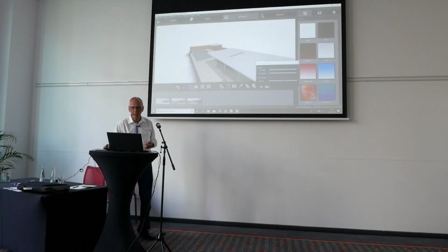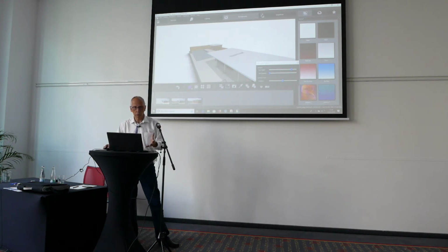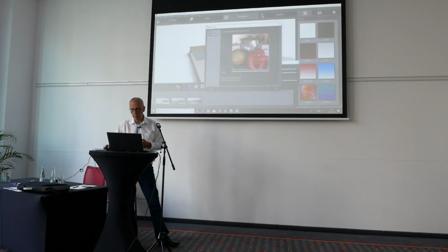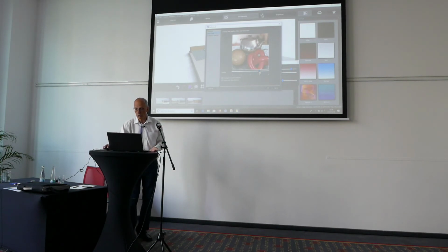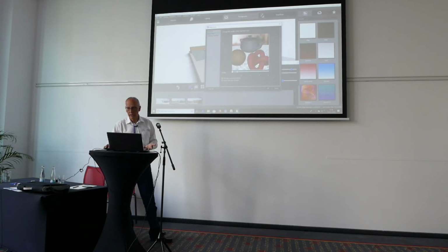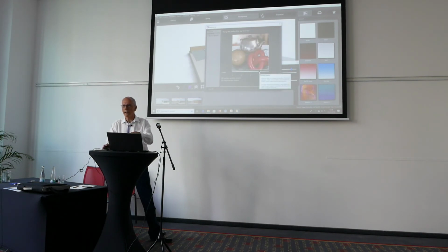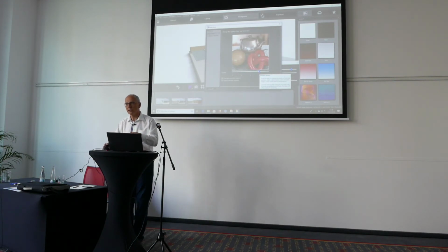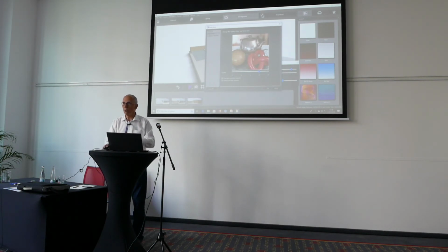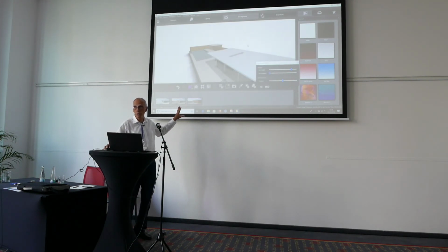And we do actually have an interface. I know some people sell a machine which may not be able to do all of this. I think in the edit preferences, we can say, okay, the real time, at the moment, oh, I've got it on 4, it's not even as good as it can be. So we can change the quality of the OpenGL rendering according to the card that's there. It has a go at doing it itself, but I must say it doesn't always get it right. It thinks the card's a little bit more capable than it is. But if the card's not capable of doing shadowing, it won't do it. So this is all Lightworks standard rendering doing this.